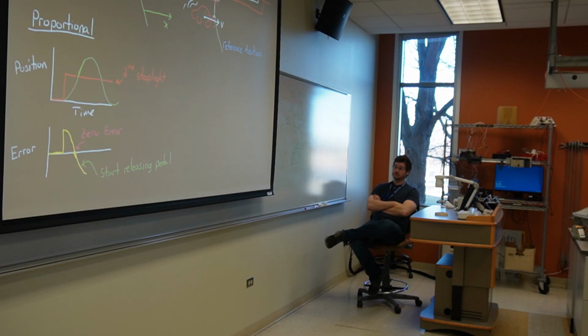Of course, more than likely, the officer will just say, "Tell that to the judge," and is going to hand you the ticket anyway. But you can avoid all of that mess by using a proportional derivative controller. When you add the derivative term to the controller, making a PD controller, you're adjusting the change in angle of the pedal based on the rate of change of the error as well as the magnitude. In other words, you recognize that you're closing in awfully fast on the light, so you better start releasing the gas pedal a bit early.